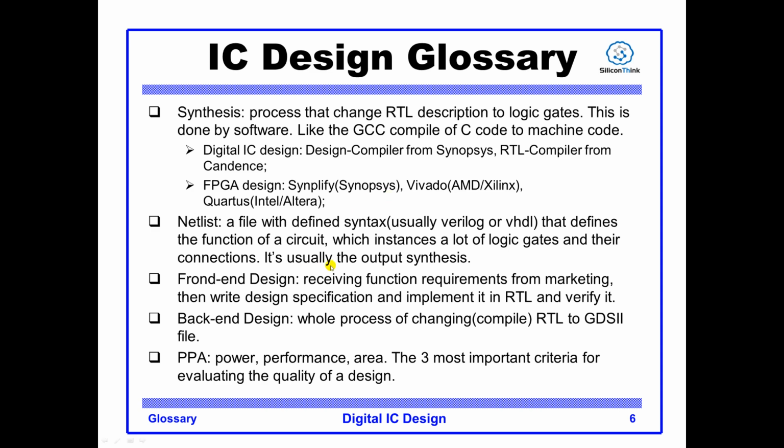Front-end design. Front-end design includes the process of receiving function requirements from marketing, then writing the design specification, implementing it in RTL, and verifying by simulation to check the function. So this course is focused on front-end design, both digital IC and FPGA design.